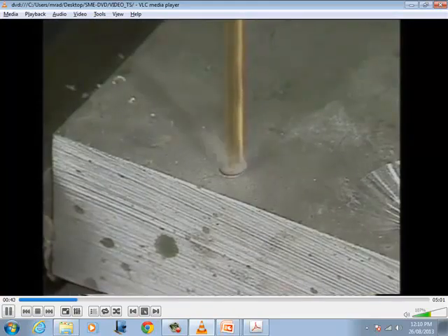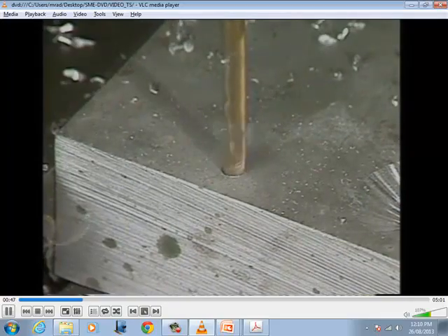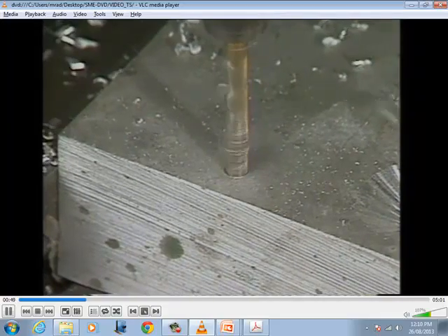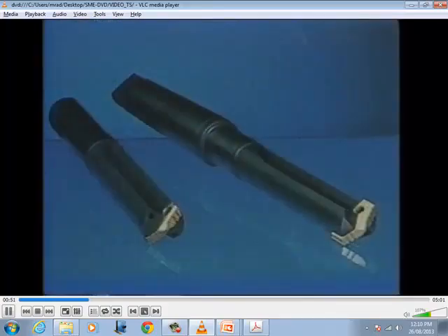Carbide drills are stiffer than high-speed steel drills, so deflection is less, cutting speeds are faster, and holes are more accurate. Carbide drills are especially useful in hard or abrasive materials. Solid drills of high-speed steel or carbide dominate applications up to about a 5/8 inch or 20 millimeter diameter. Spade drills and indexable insert drills cover the larger size ranges.